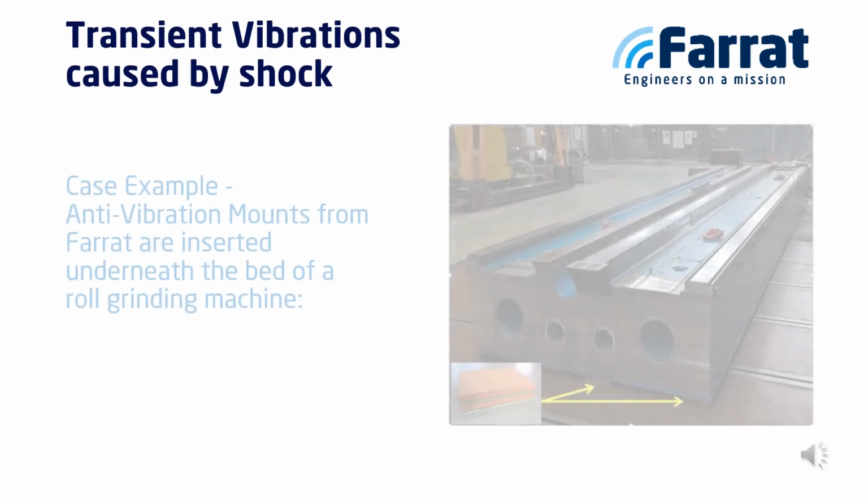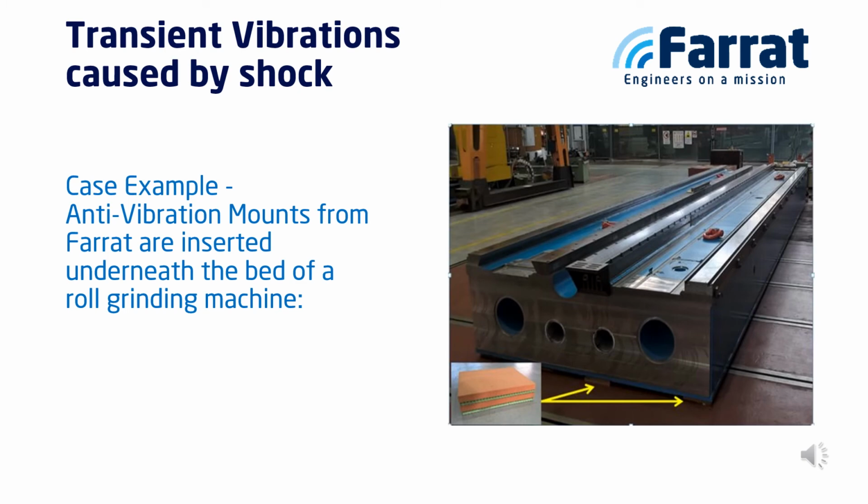In this recent case example, anti-vibration mounts were inserted underneath the bed of a roll grinding machine to reduce the transient vibrations caused by shock. You can see on the picture where the mounts were positioned to improve the performance of the machine.